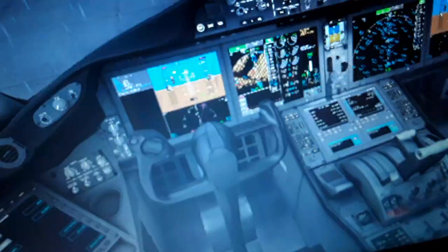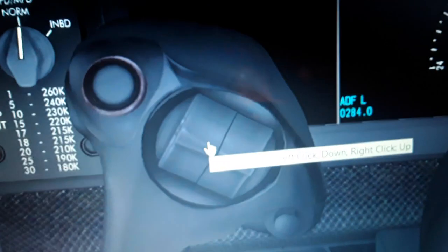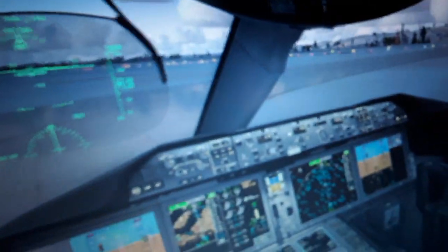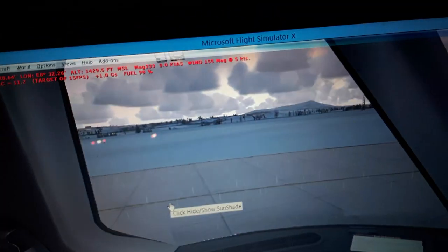So it's very important to trim the aircraft, the jet aircraft, as you fly. So one more time, you can see we trim the horizontal elevator up and down like this, or in some other aircraft you trim the horizontal stabilizer, the whole surface of the horizontal stabilizer, like in the Airbus. So you can see also an aircraft now is coming for landing.